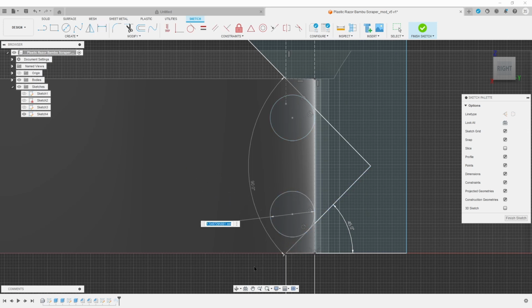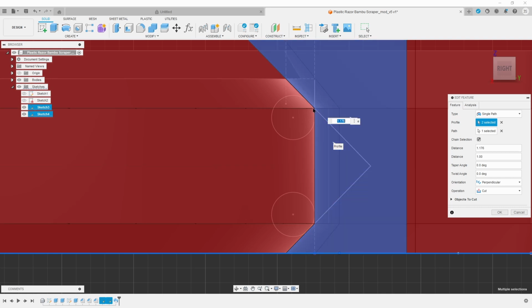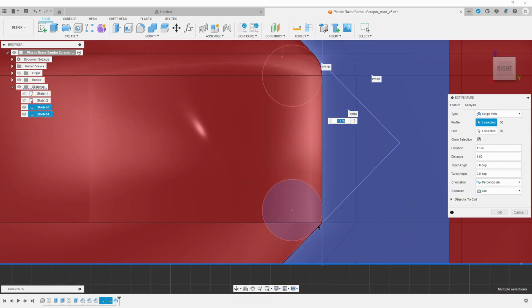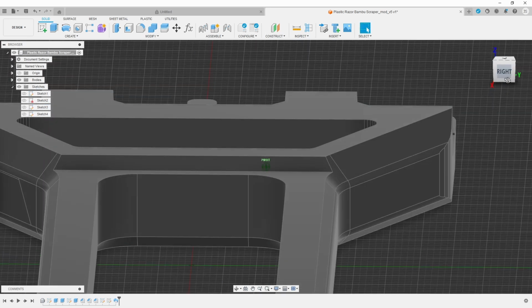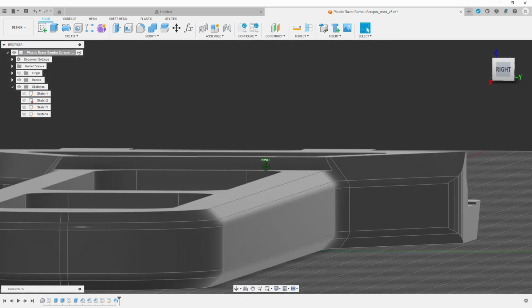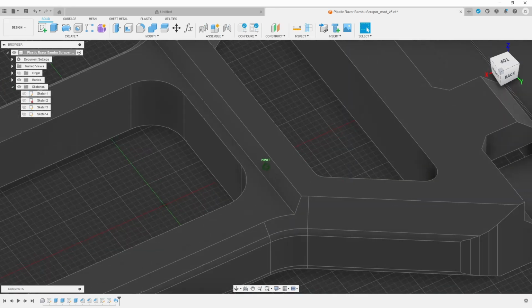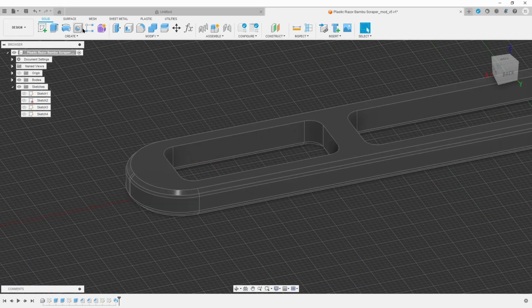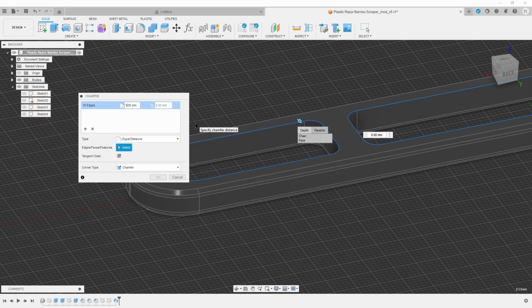And so the beauty of this technique is it allows you to create a chamfer and a radius in the same feature. So I'm going to go back into my sweep and I'm going to change my profile to include that radius. And now I have the chamfer and the radius, and it smoothly blends across that feature. And then where the tool ends, it blends out into nothing. And it's very clean, really sharp, and a great technique. I encourage you to apply it in circumstances where it gives you the outcome that you want.